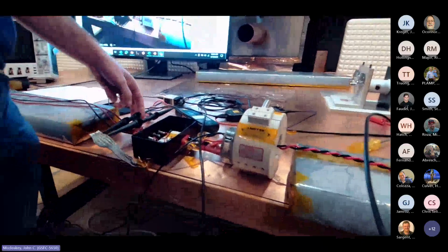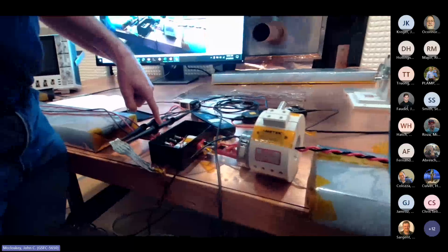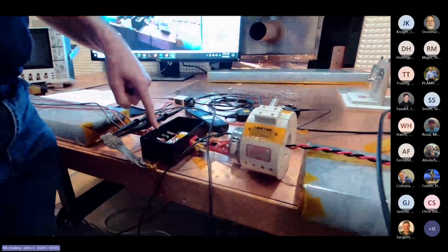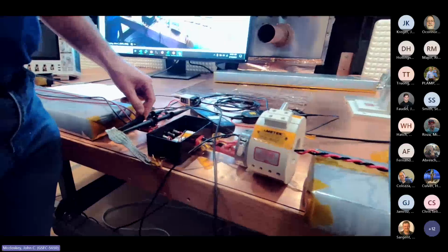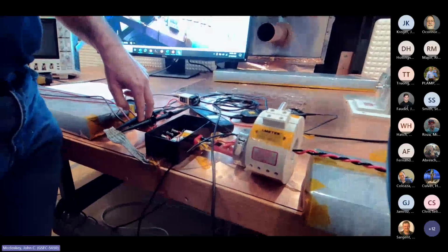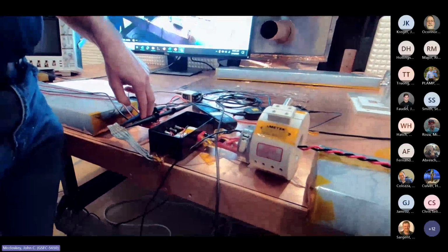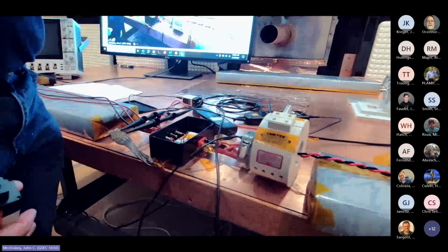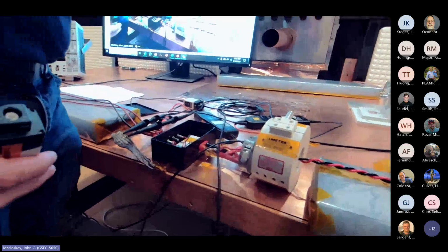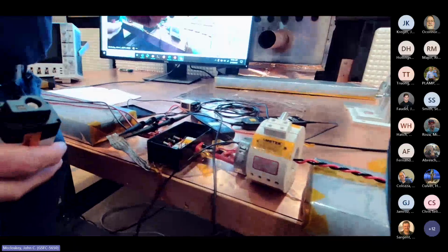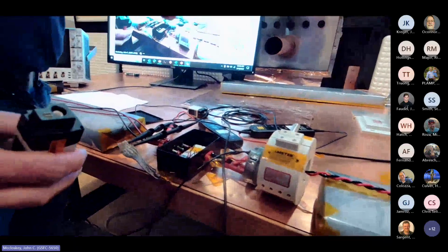Then I'm also monitoring the secondary voltage, the 15-volt output of our power converter, with respect to the braid. Because when I looked just across the output differentially, it has decent common mode rejection, and you didn't really see much. I'm more interested in what is the common mode that's getting through. So we're going to look at both of those.